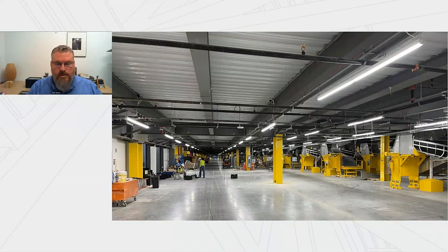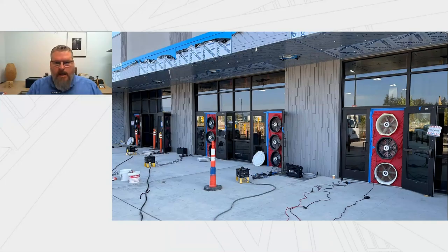It's 4 stories, but the great thing is it was an easy single zone because everything was very open between floors and across floors, just a lot of distance. We had thousands of feet of cable. There weren't enough outlets and power sources, so we did have to bring in generators and power points in order to test it. When you do the calculations on this for a standard blower door fan, it came out to requiring about 80 fans. I'm not aware of any test agency in the world that has 80 fans themselves.